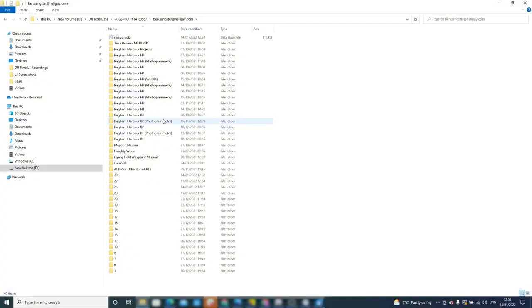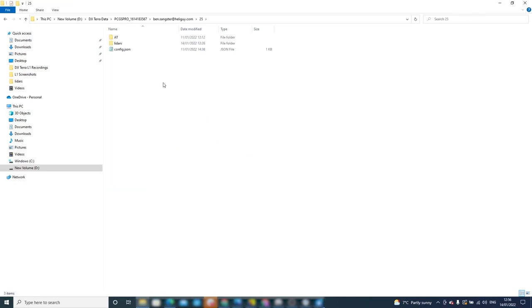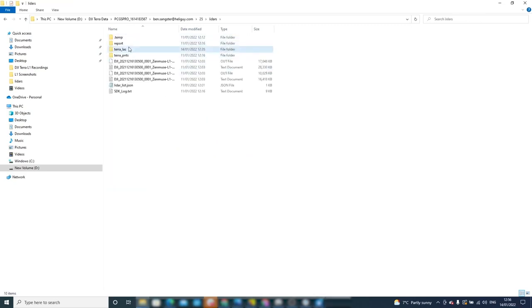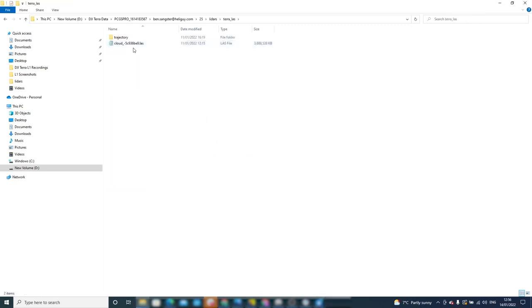Let's look at the result files generated from DJI Terra. Once the data has been processed, the file will be named with a number and not the project's title. This can be found in the same drive as your DJI Terra application. It should be under DJI Terra Data. The first output is the LAS file. This industry standard format is in the version v1.2 and records information such as RGB colour, reflectivity and the echo that each 3D point belongs to.